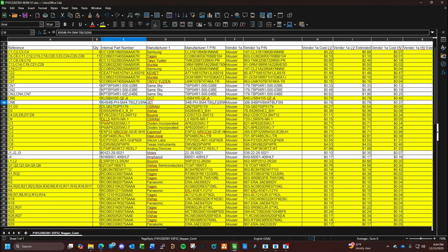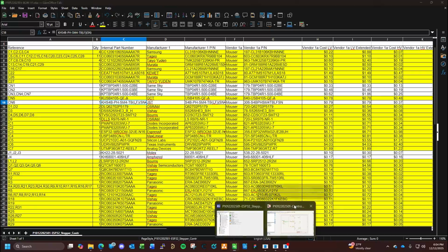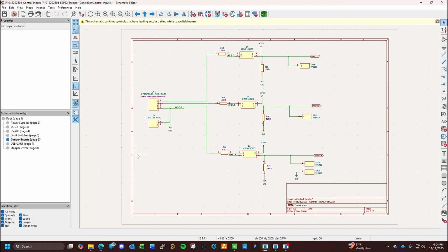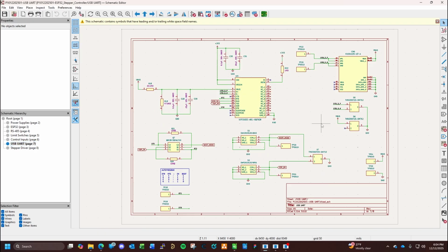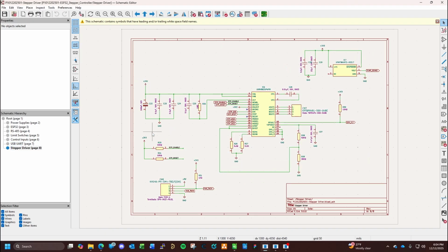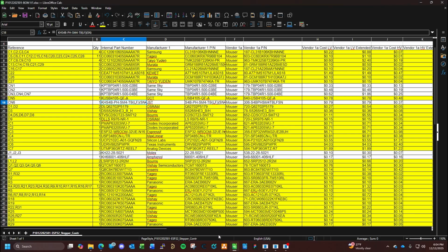Well, these are actually the through hole part. Okay, all right, yeah. So CN6. Let's see what that is. Make sure that's not a through hole part, because that's an SMT part and I screwed up something. CN6. CN4. I bet you that's... Yep, that is an SMT part. We will double check that. We'll ignore that for now. But everything else is through hole.